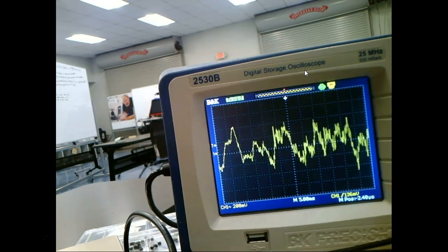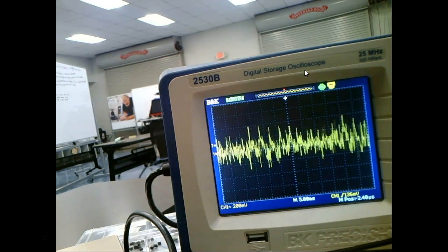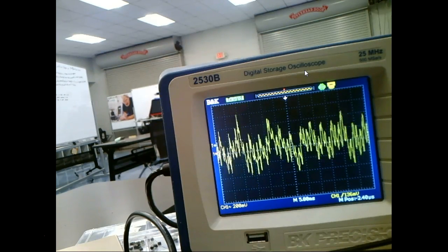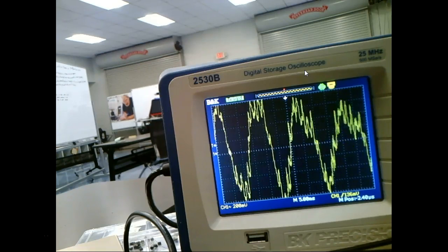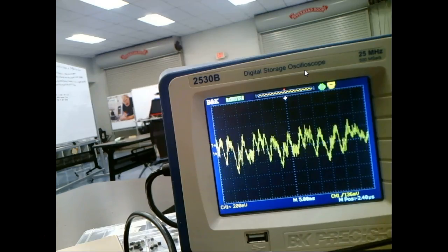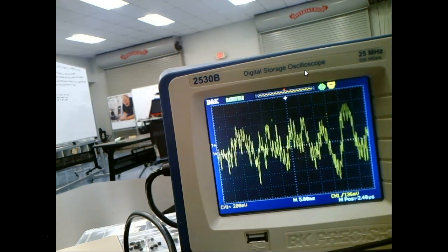But what we do in our lab, of course, is we look at sine waves, because that way, what would be the gain of this amplifier? It'd be impossible for me to calculate to see if the gain was right, because this is what? It's all over the place, right? You understand? But it's just a combination of sine waves. So normally when we troubleshoot an audio amplifier, we can look at this, and we can tell if something's there or not there, so we can go through a stage. But if I was trying to check the gain or the bandwidth of the amplifier, then I would use a function generator. What is the bandwidth?